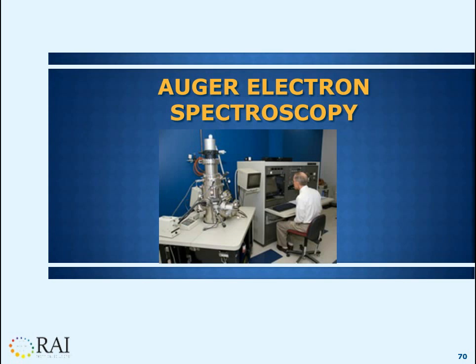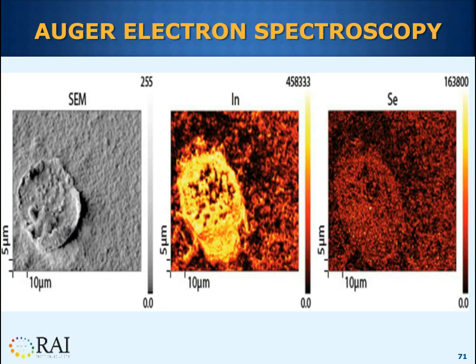Auger electron spectroscopy is excellent for showing a visual image of the chemicals and elements on the surface of a material. This particular slide is an example of what Auger spectroscopy can do in helping me as a forensic engineer. I can visually see how the chemical elements are distributed on the sample surface, which is a very powerful tool in explaining my results to a judge or jury.